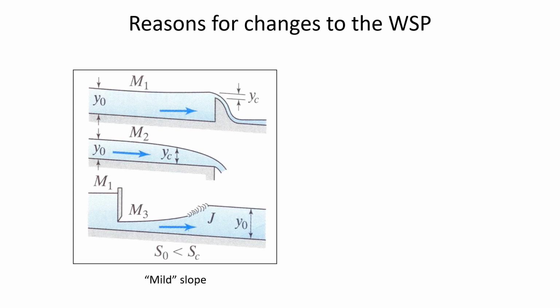So let's look at some more water surface profiles and the physical things that could cause them out in the world. So if you had water flowing over a spillway, so this is like a reservoir behind the spillway. So you had normal depth that was approaching some obstacle that causes pooling. An M1 profile connects the normal depth to the spillway. So water is gradually getting deeper. We have a mild slope.